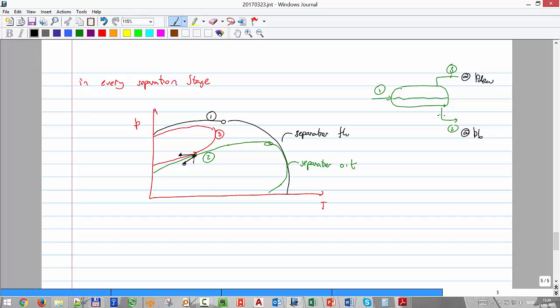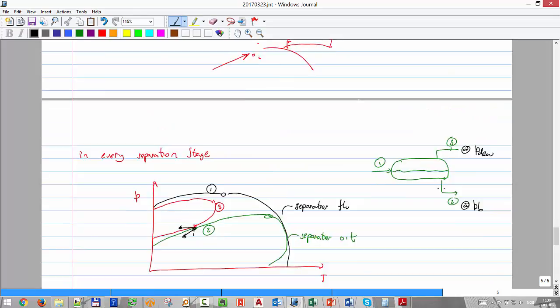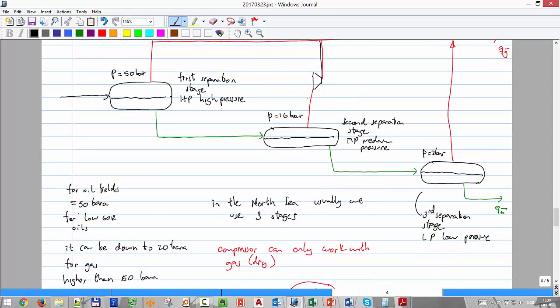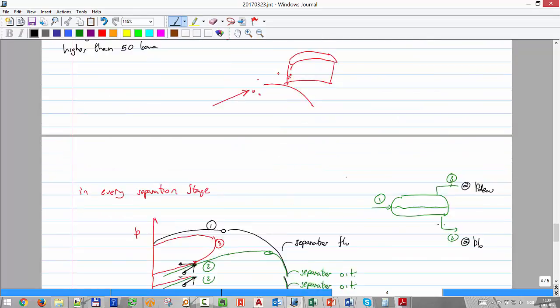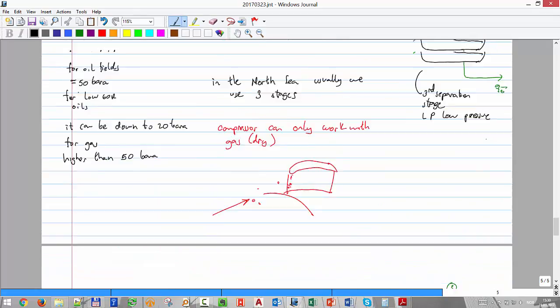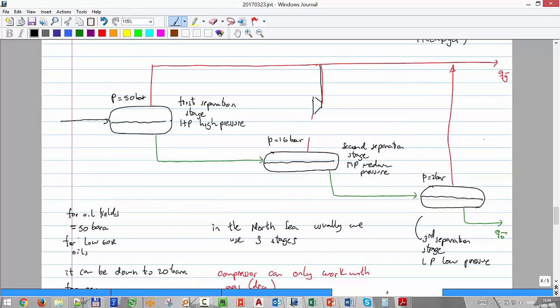Is that clear? So then the solution: before the compressor I have a very high risk of introducing droplets of liquid to the compressor, or bubbles of gas to the pump, which also doesn't like any gas. So what we make is, first I will force it to release part of that liquid, so I will put a cooler.